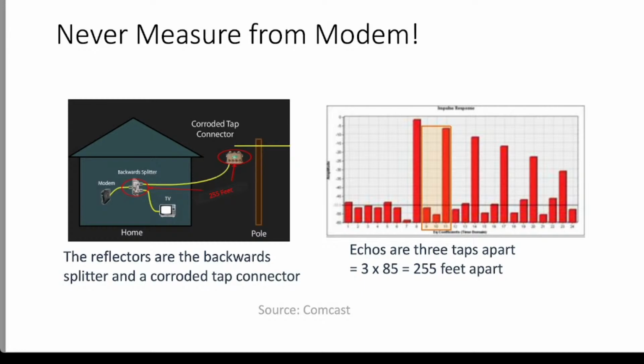So this is interesting because the insertion loss on a splitter is the same, front to back, back to front. It's that port-to-port isolation. So in your diagram here, the TV would get screwed, right? The TV would be getting like 20 dB lower than it should be. What I could see happening here is the modem transmits in the upstream, hits the back of the TV that has a poor return loss to begin with, and reflects back and forth right there. So having that leg go into the modem, the through loss of that leg is the same regardless of it turning around or not. But the fact that the modem's transmit signal can easily get to the TV, that's where you're supposed to have isolation.